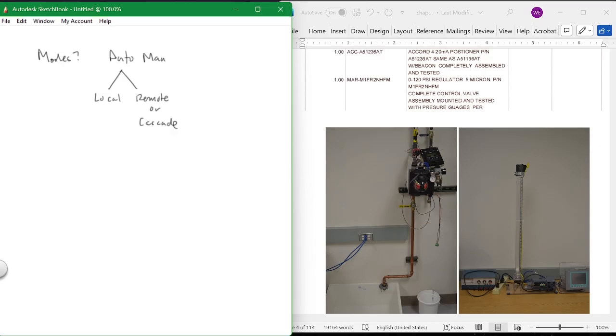It's a wonderful lab. I'll just give you an example. If you set up P equal to 0.4, I to about 1, and D to 0, it worked wonderfully. If you went to 0.8 or higher, this thing started to oscillate dramatically. It sounded like a drunken mule.